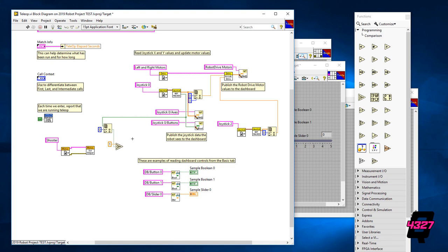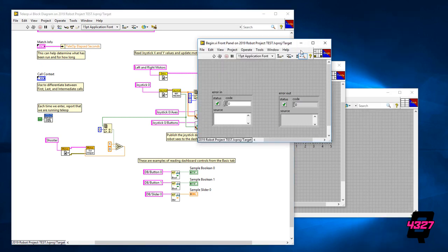As a pro tip, if you're programming an intake system, you may want to make this value a small amount like 0.1 or negative 0.1 to act as a holding voltage. This value doesn't really move the motor, but it makes the back drive a greater challenge, and that holds your game piece in your robot. Okay, finally, wire the right side of the true-false gate to the set output icon of your motor like we previously did with the axis. There are a lot of fancier things you can do here, but this will get your motor up and running.